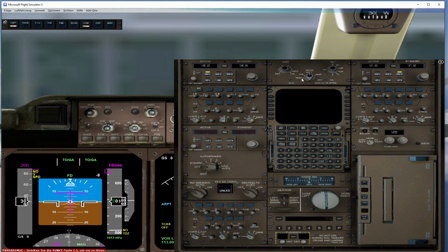Yeah, this is the weather right now. As I said, it's not simulated here in the EMG. This is the center CDU, where we usually work with our ACARS system. Obviously on the EMG simulated. Rudder trim, of course, is centered. You only need this during engine failure. So if you have a yaw moment, you can counteract this. Aileron trim, you need to use both the switches at the same time so that the aileron trim is working.